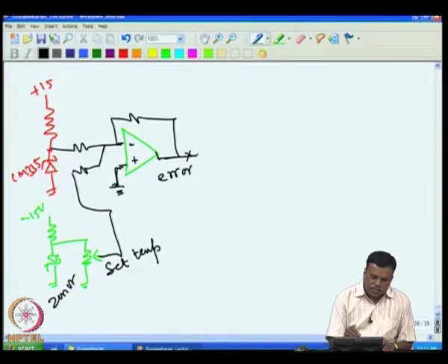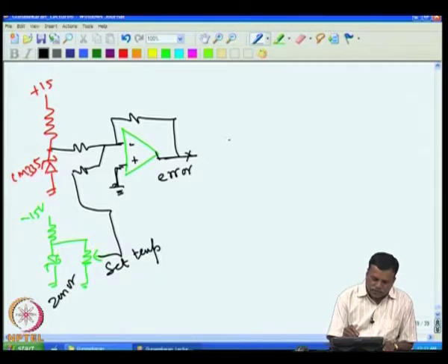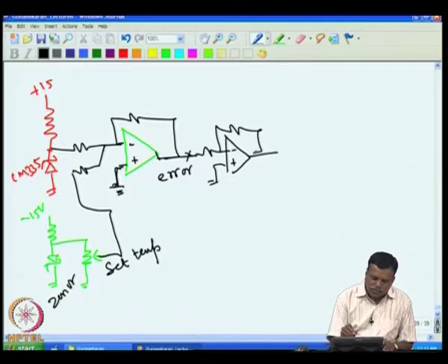If you actually want plus, we can change it, or we can invert it, since it is an error voltage that we have to amplify and then add. So, if you want, we can invert it so that it becomes plus. Essentially, when temperature goes up, more plus voltage is coming here, and that makes this one go minus and this one go plus.